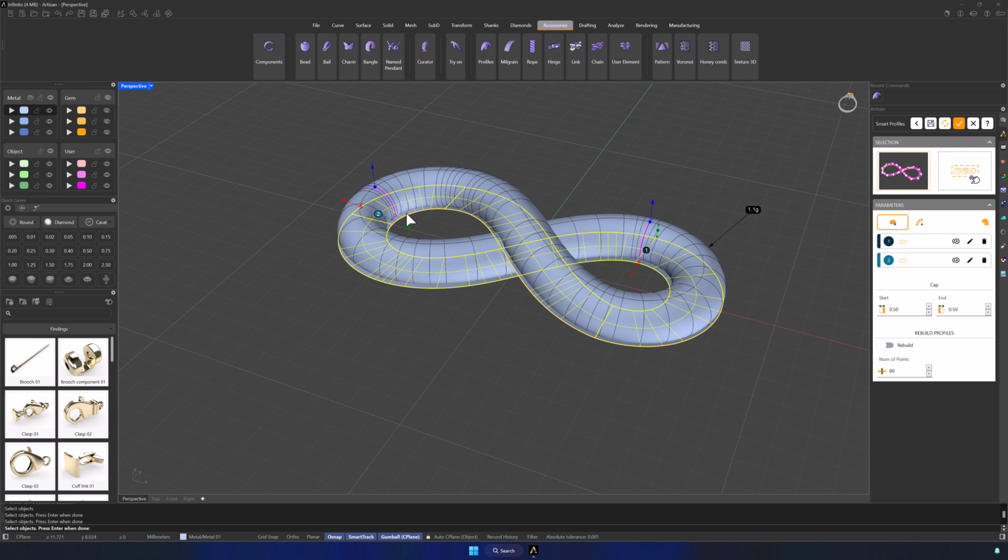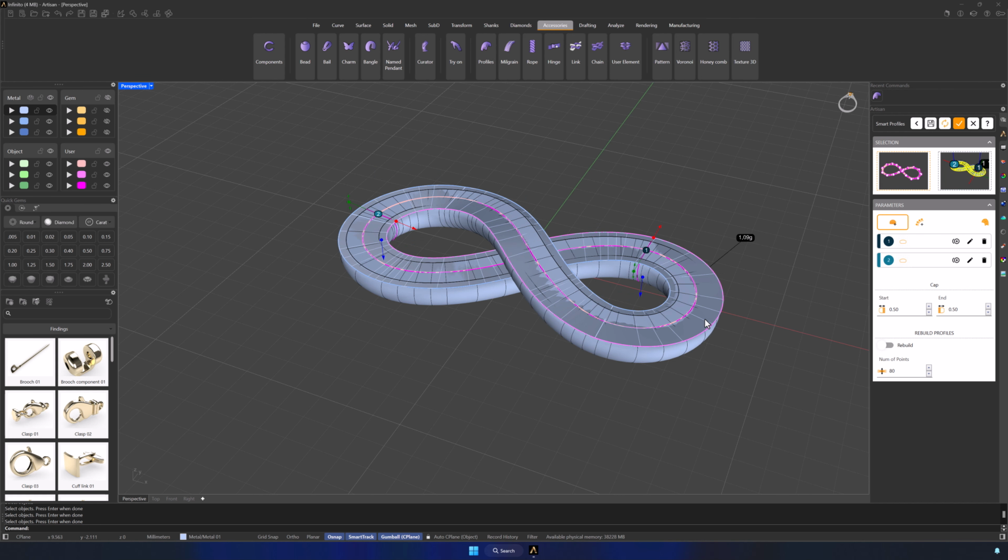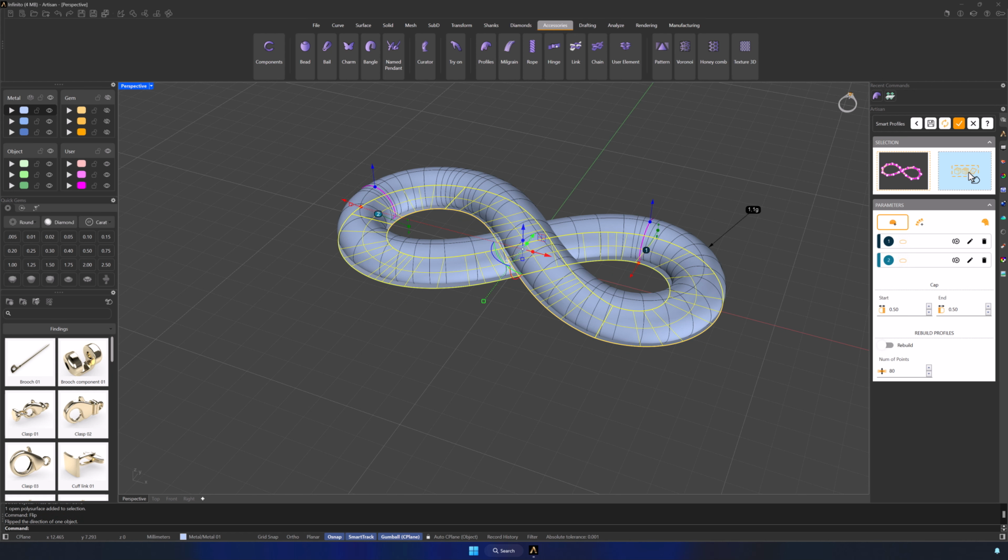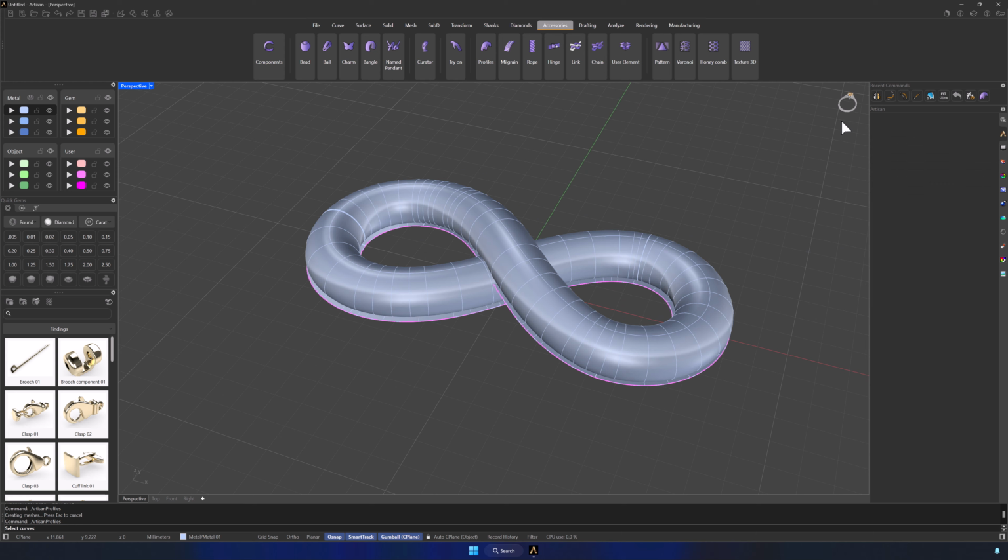If you see the element positioned at the bottom, it's because the surface is rotated. Simply select it and type Flip in the command bar to adjust the orientation. Then add it to the selector again to update the position. Now click OK on the command to create our element.